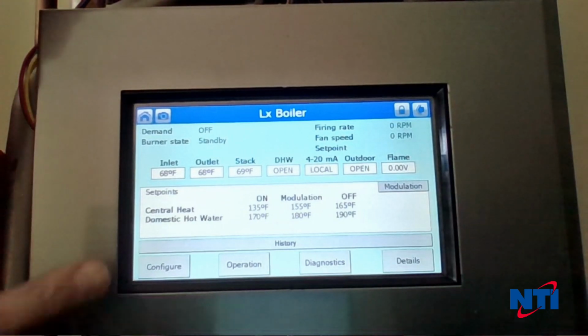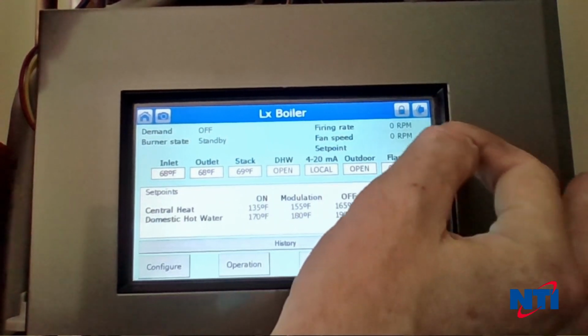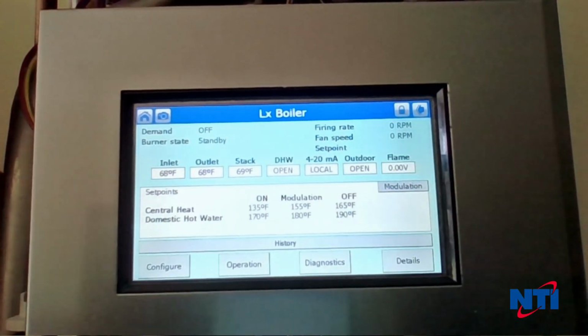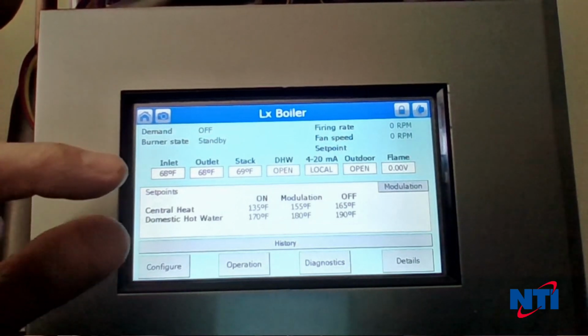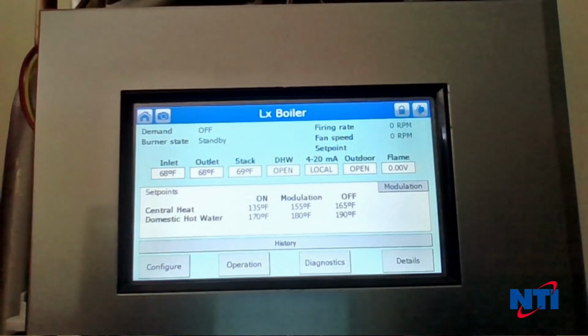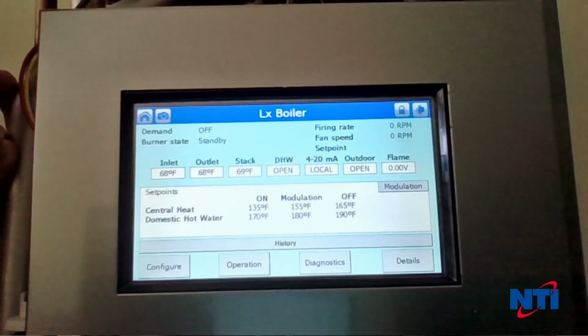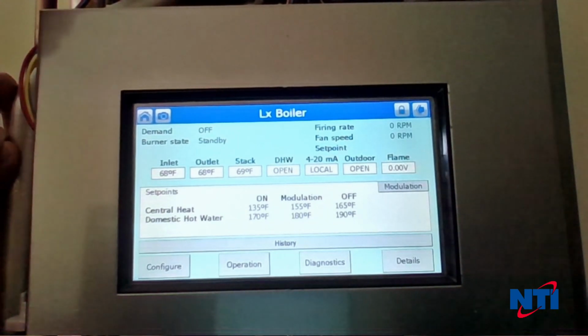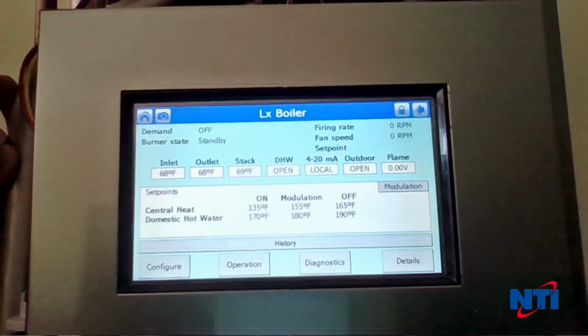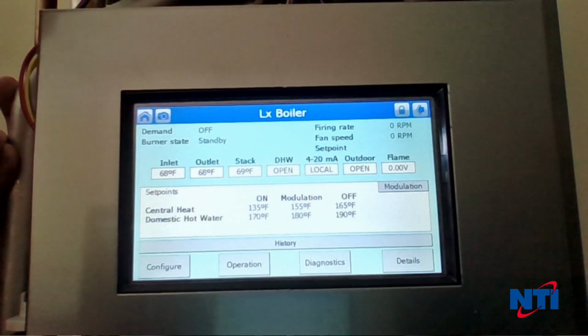And if you ever see that, what you want to watch is look at these two numbers, and as long as they're closing the gap and they're becoming more and more equal, you don't have to worry about it. What's happening is just the fan is slower to respond than what the controller wants. If you see, for example, fan speed of 0 and a firing rate of 4,000 and a hold 62, at that point maybe you've got a problem and you'd want to start to troubleshoot.